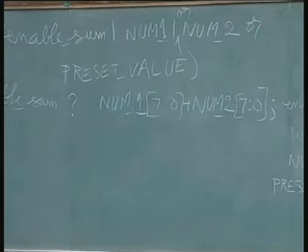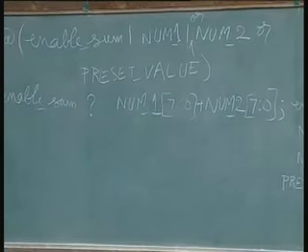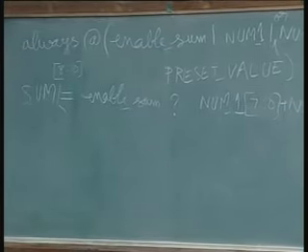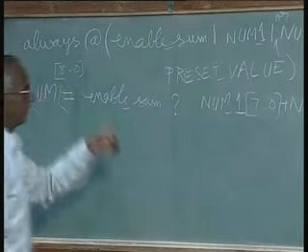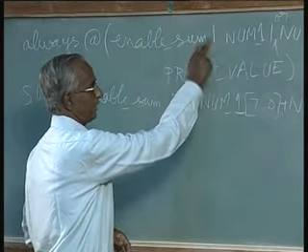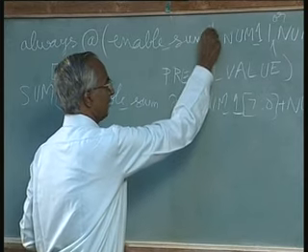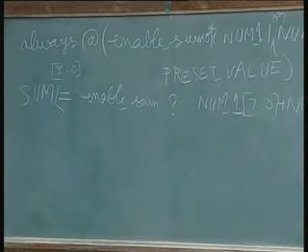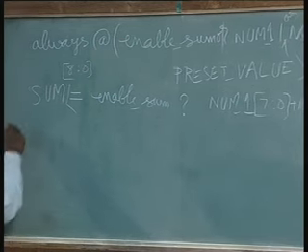And similarly, many people, especially novices, make the mistake of putting a logical OR as such. So, this is not a valid thing. So, what we have to do is put a bitwise OR. And now similarly we will write for the other three outputs, that is match.